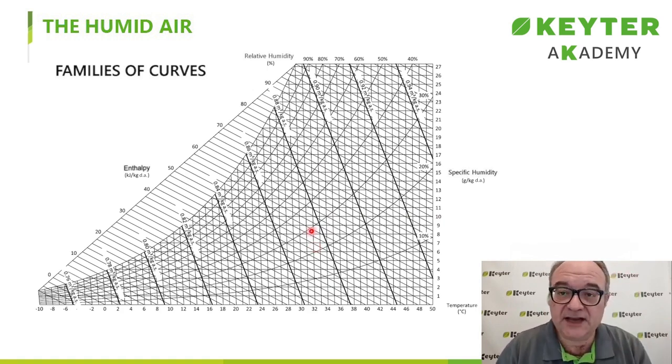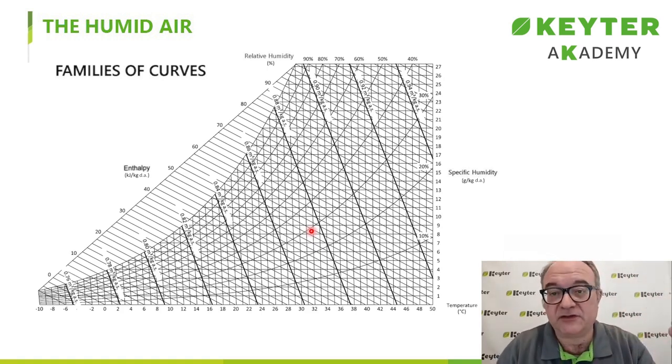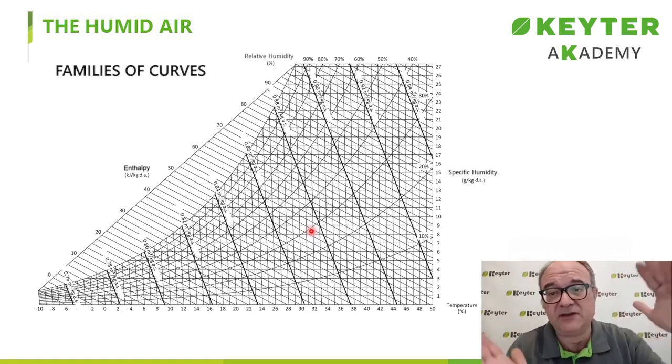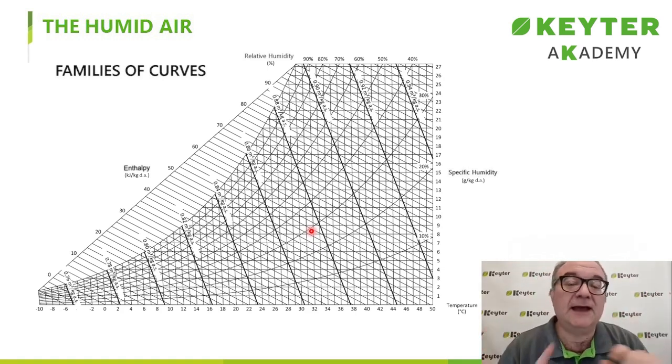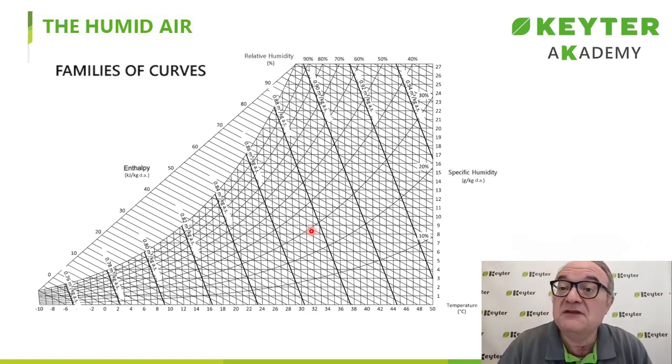Each psychrometric diagram is made for an altitude, for an elevation above sea level. Changing elevation, the diagram changes. The higher we go, the smaller the diagram gets. Hence, if we start with an unsuitable diagram for the desired work area, all calculations will be inaccurate and incorrect. This, for example, is for 0 meters above sea level. To work at 100, 200, 300, 400 meters above sea level would be valid. It would be a very accurate approximation.